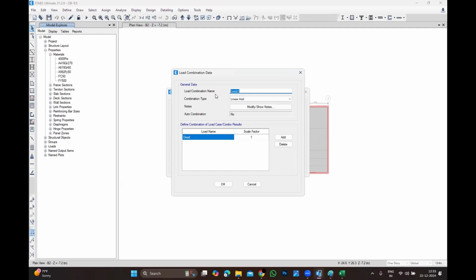That is the reason I told you we are not going to check the serviceability for this model. This model is called the cracked model. Why is it called the cracked model? Because you already applied the stiffness modifier by reducing the moment of inertia. We are going to use the serviceability model, keeping all modifiers as one, using 100% of the moment of inertia. This model is only for the design, only for the analysis to extract the forces.